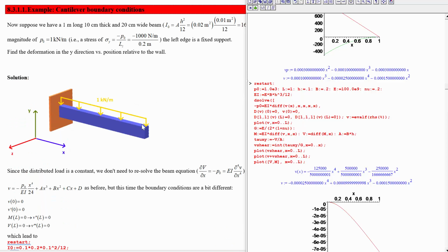So to solve this problem, we have two different methods. Our old statics method to find out the internal bending moment and shear force, and then convert that into displacements using the new elasticity methods for each of those that we have from last week and this week, or this new method using the beam equation, which has us not solve the statics problem, but directly solve this fourth order differential equation. Another thing that's great about this beam equation method is it lets us solve problems that we could never solve with that statics stuff from before.